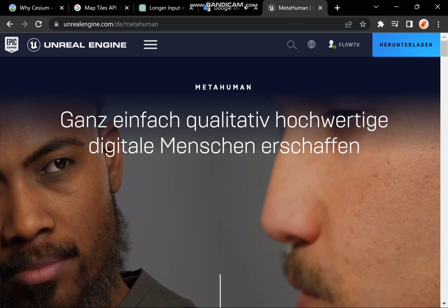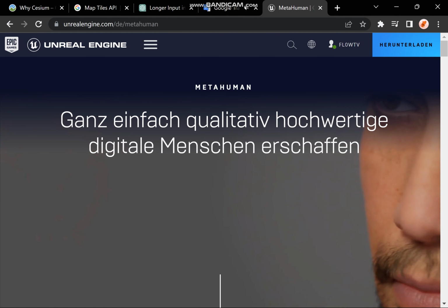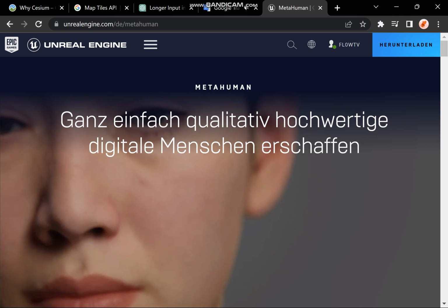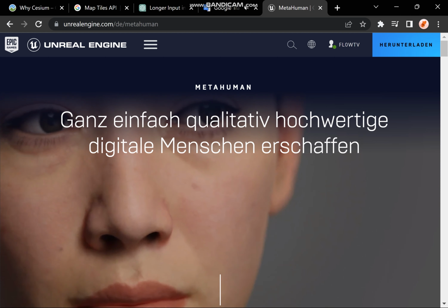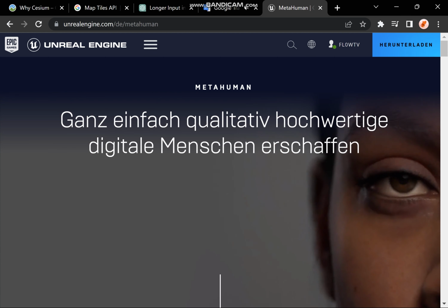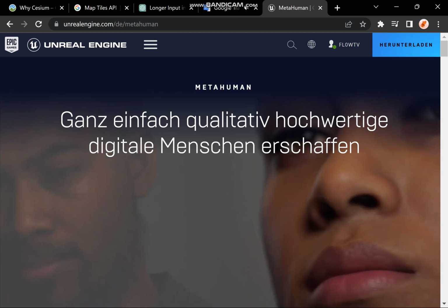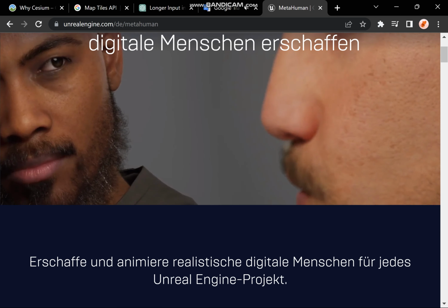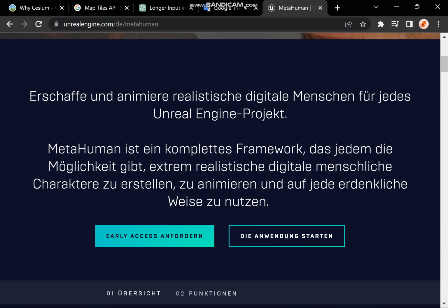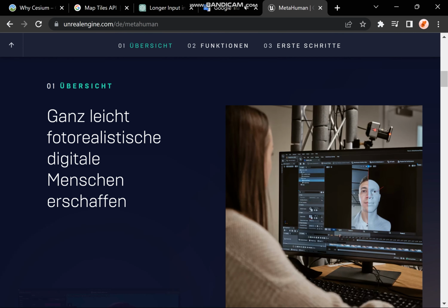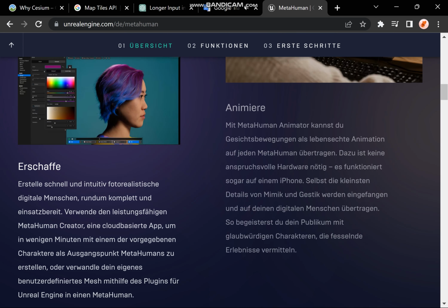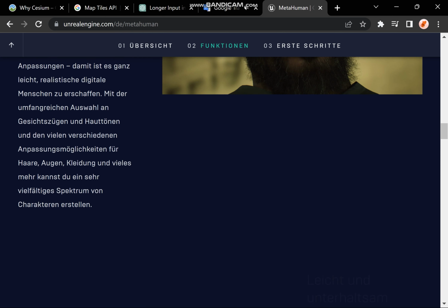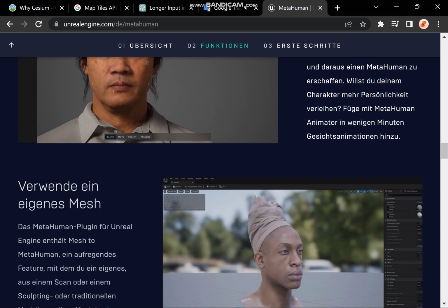This feature provides a minimal set of HLODs using instanced static mesh components, ISM, or visible proxy meshes over unloaded World Partition grid cells, reducing the number of draw calls and boosting performance. These proxy meshes are generated using the original actor geometry and are simplified to reduce memory usage. For more, see the World Partition Hierarchical Level of Detail documentation.